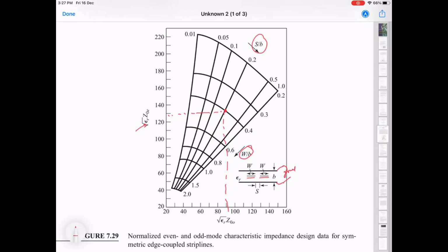Each transmission line has a characteristic impedance of Z0, and they are not talking to each other, they're far enough. But I can still define an even and odd mode, right? What would be the odd mode impedance in that case?